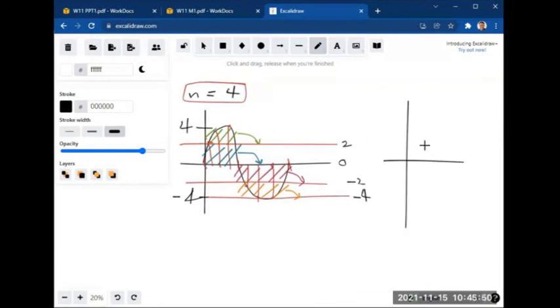Okay. So if we will draw this one in digital, it will approximately look like this. This part will be 0. This part will be +2. This one will be 0. This one will be -2. And then this one will be -4. So the higher the resolution, or the higher the n, the more accurate the signal will be to its analog origin.